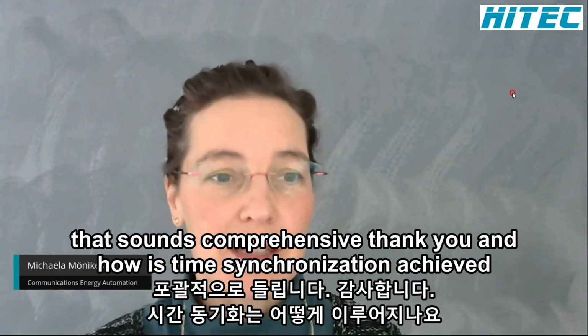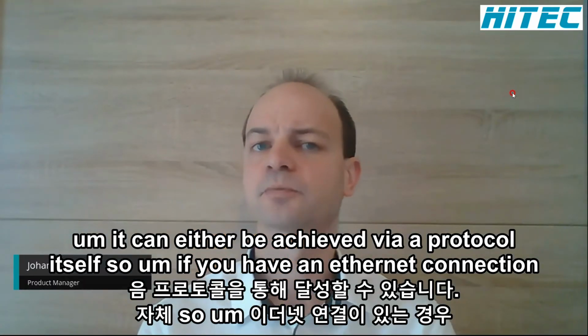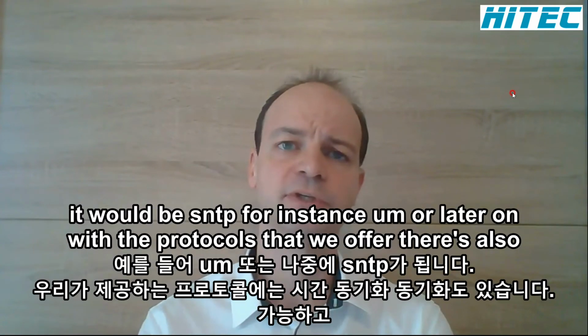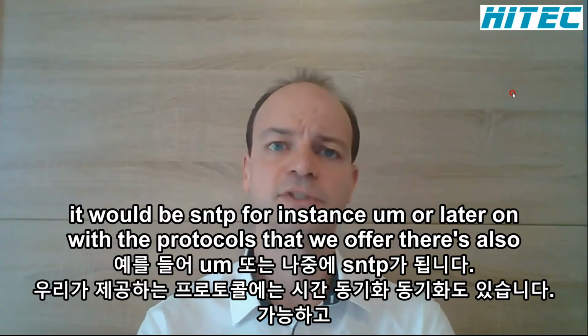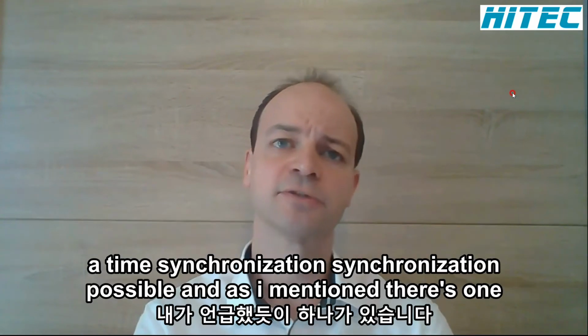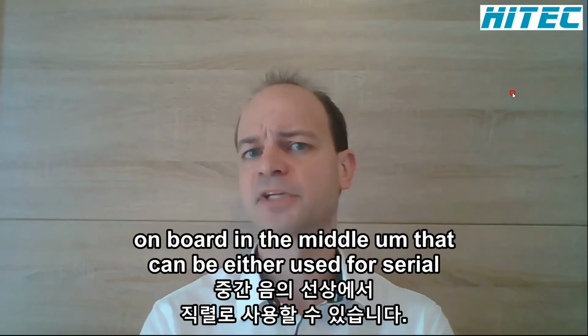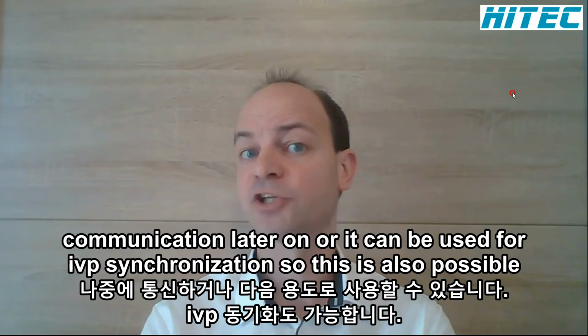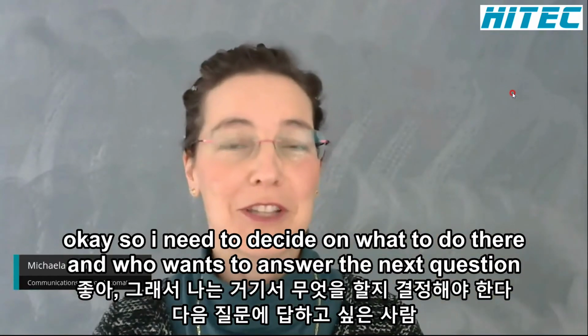And how is time synchronization achieved? It can either be achieved via the protocol itself. So if you have an Ethernet connection, it would be SNTP, for instance, or later on with the protocols that we offer, there's also time synchronization possible. And as I mentioned, there's one port in the middle that can be either used for serial communication later on, or it can be used for IRIG synchronization. So this is also possible. Okay, so I need to decide on what to do there.